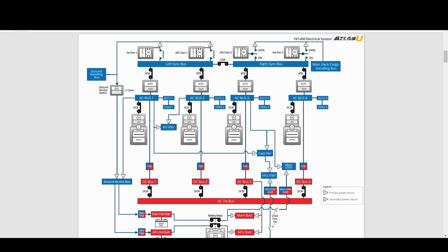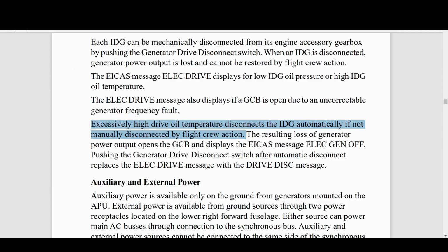What condition would automatically disconnect the integrated drive generator if not manually disconnected by the flight crew? Excessively high drive oil temperature disconnects the IDG automatically if not manually disconnected by flight crew action.